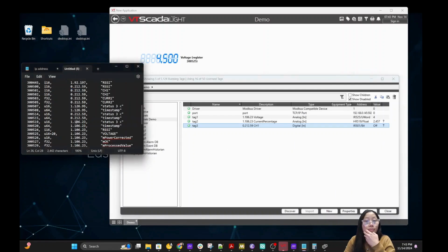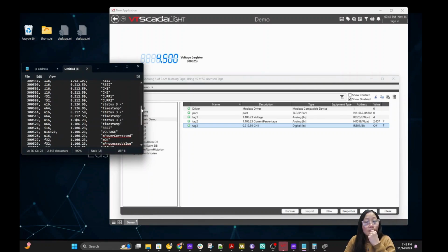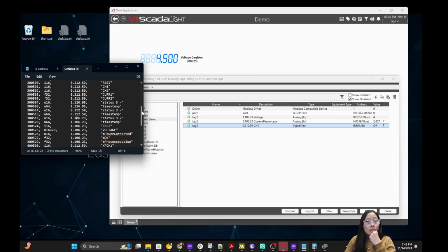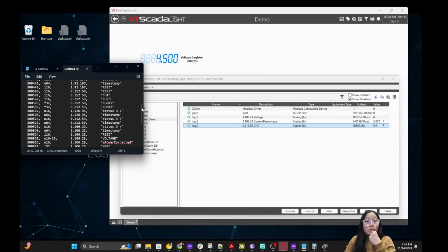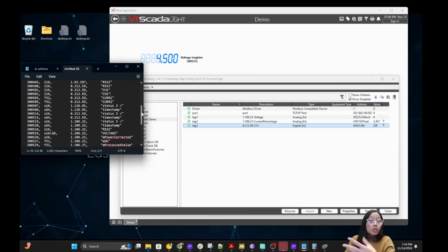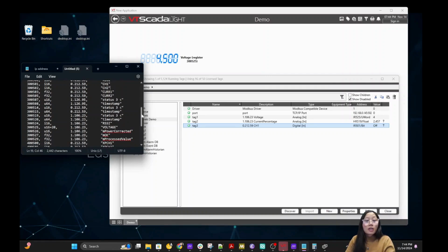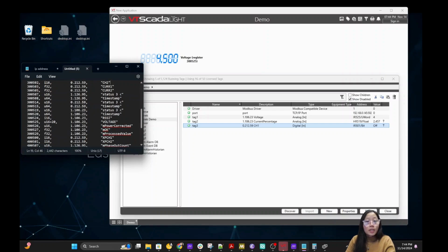All right. So you can also control devices from your SCADA system through Modbus. So for this relay node, you can actually toggle channel 1 or channel 2, which will then input a 24-volt signal out of the sensor, which could control an equipment that is wired on a contactor, for example. Which is the case for me. So I'm going to add this tag.